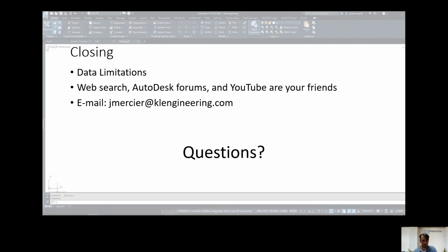All right, well, that really wraps up the show and tell portion of the presentation today. Just wanted to quickly, in closing, discuss the data limitations a little bit. Obviously, your design is only going to be as good as the data that you have input into that design. And we don't really know for sure how great the data that you get off of a county GIS site is. Sometimes those surfaces can be 10 years old. So you have to take that into account when you're considering what you're going to use that LiDAR surface for.